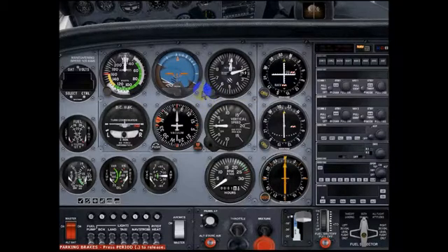Trenton Mercer Airport is 213 feet above sea level. So we want this needle to be slightly above the 2. It's saying 205 now. I'll bump it up. No, it's saying 214, so okay, that's a more reliable, better indication.